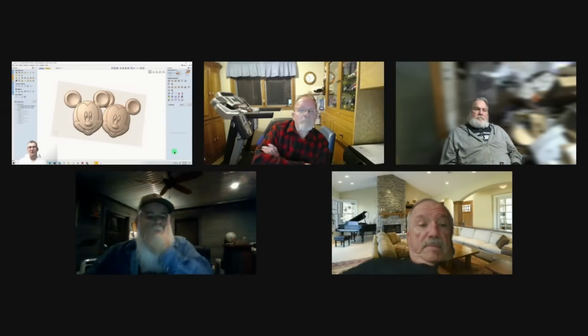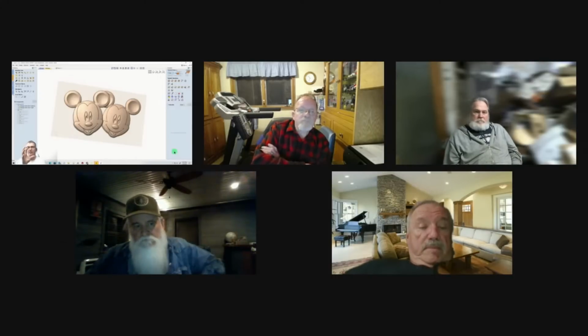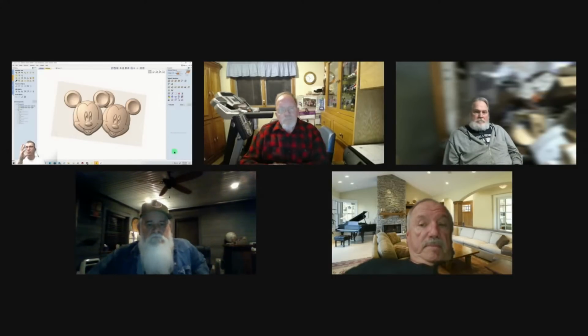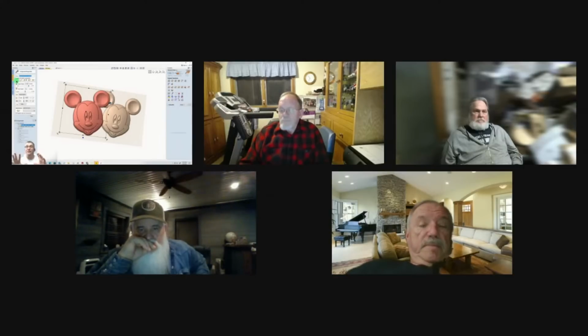All right, well, ladies and gentlemen, that is it. We ran over 30 minutes. Sorry about that, but I really wanted to conclude the properties. In that property box, that spanner wrench, when we have a model selected, we changed shape height, we added a little base height, we changed combine mode, add and subtract, but we didn't talk about those two components, tilt and fade. Now that completes the big picture of that particular tool.